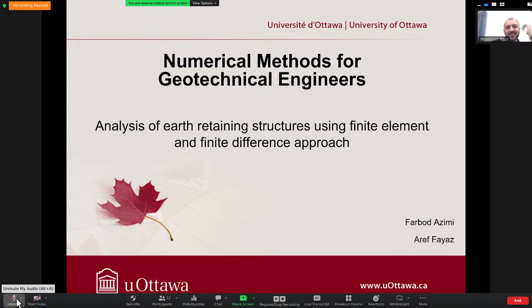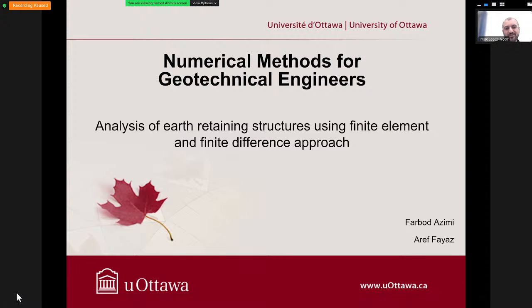So in a case where, for example, I have to put a pile in the slope to stabilize it, yes, we would recommend using a finite element method to model it, because modeling a 3D element into a limit equilibrium problem is always time consuming. So in that case, yes, you would use that.